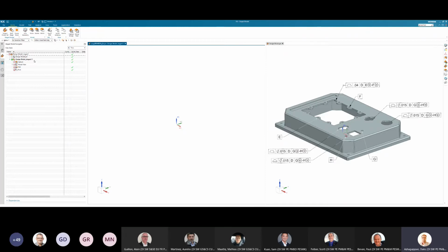So in this case, I'm going to start with this one. I'm also given an option to edit this. You can give a name, saying operation 10. If you want, you can also provide some information to this, saying that you want to mill 4 pockets, for example, on top side using datum. So this is the information you're going to give to the downstream process team. I'll add this note here. You can change the name of the stage, so you can see that changed.